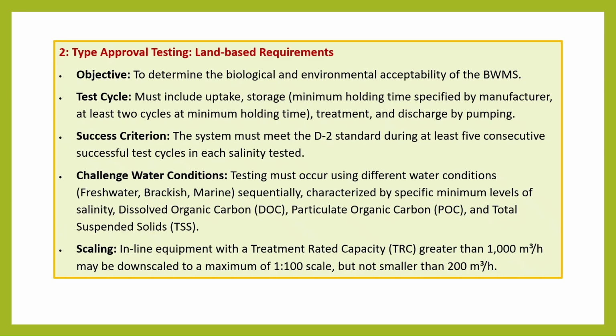Type approval testing, land-based requirements. Objective: to determine the biological and environmental acceptability of the BWMS. Test cycle must include uptake, storage, minimum holding time specified by manufacturer at least 2 cycles at minimum holding time, treatment and discharge by pumping. Success criterion: the system must meet the D2 standard during at least 5 consecutive successful test cycles in each salinity